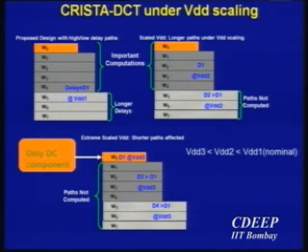So now, if I'm able to scale my supply voltage down from the first case to the second case, such that W5, W6, and W7 are not computed, because if I scale my supply voltage down, they may not give me the right computation, it turns out I get an image quality which is quite different from the case where I scale my supply voltage even more aggressively, so that I don't get anything other than W0. If I only get W0, then I'm going to get some computation which is quite different from what I get with W0, W1, W2.